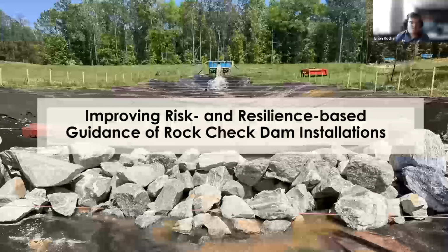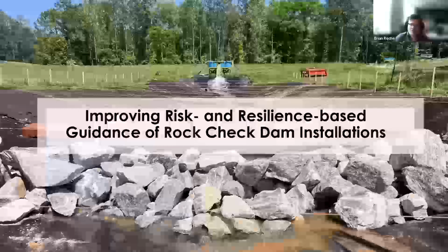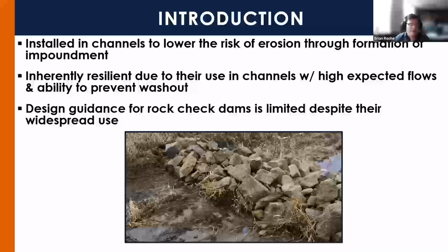From here, we're going to touch on some tests I did recently for the Iowa DOT on improving their rock check dam standards, which we also use to increase their risk and resilience-based design guidance. A rock check dam is typically an installation of rock in channels to lower the risk of erosion by slowing flow through the formation of impoundment. These are inherently more resilient than some other ditch check practices due to being recommended for use in channels with higher expected flows. We also found that design guidance for rock check dams is limited despite their widespread use. We found them in effectively every single manual we looked in, but there was really no site-specific guidance outside of their spacing.